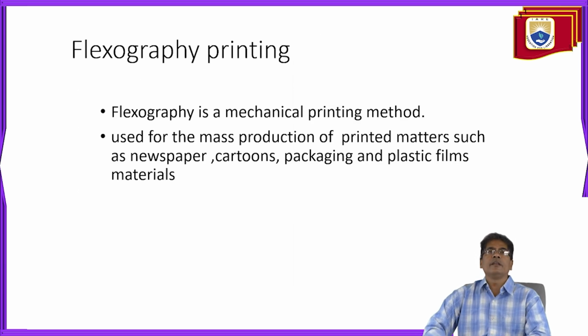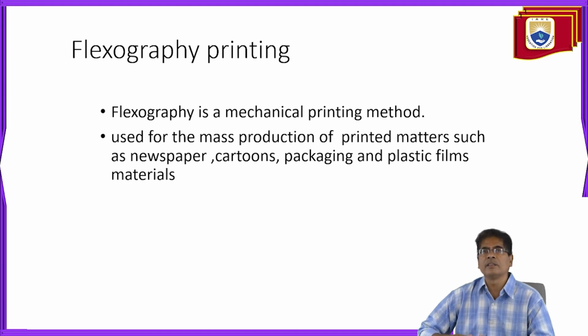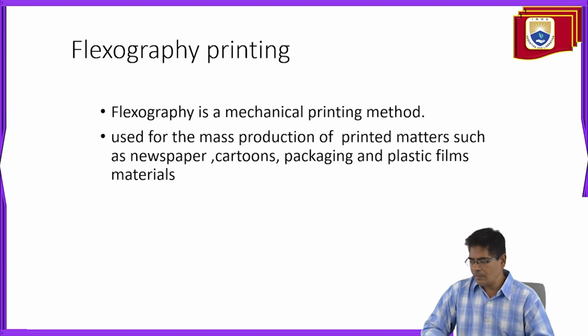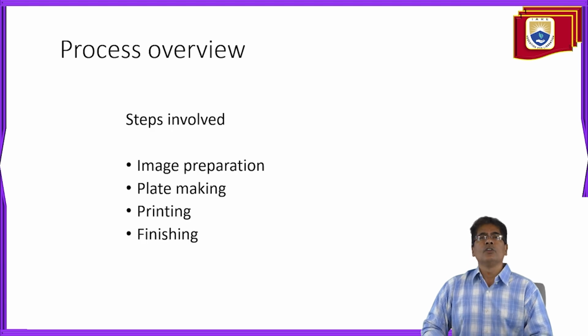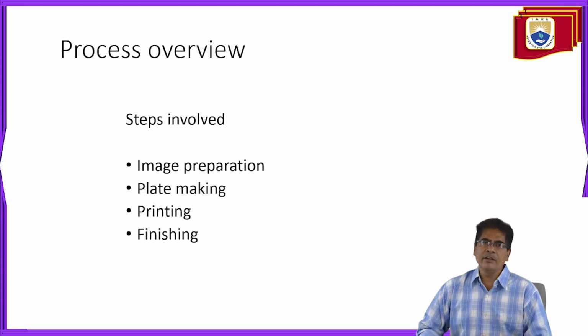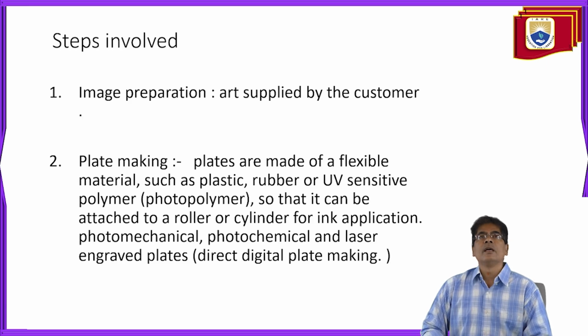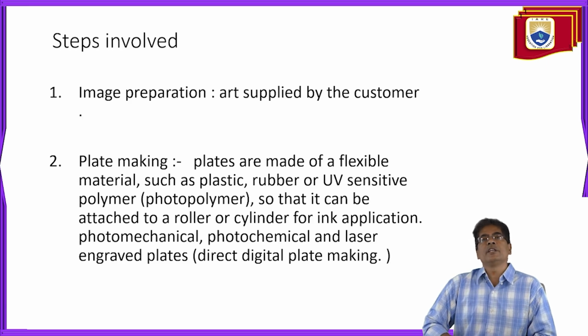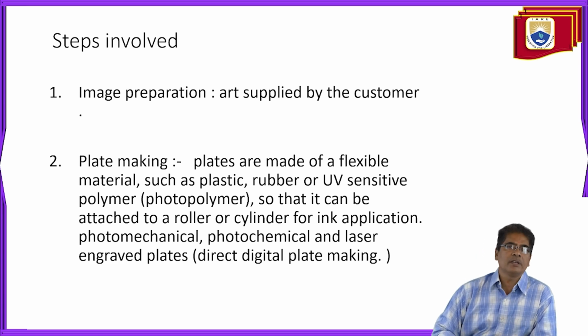Another one is flexography printing. Flexography is a mechanical printing method used for the mass production of printed matter such as newspapers, cartons, packaging, and plastic films and plastic material, right? So the process overview steps involved are image preparation, plate making, printing, and finishing. In image preparation, the art is supplied by the customer.